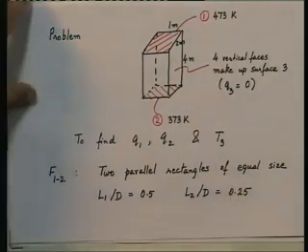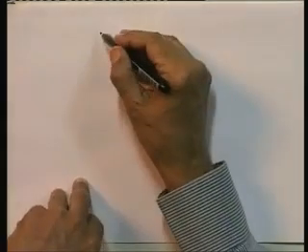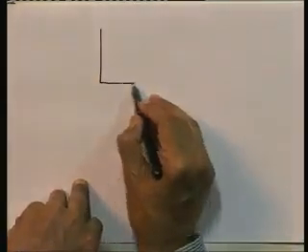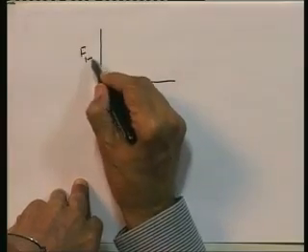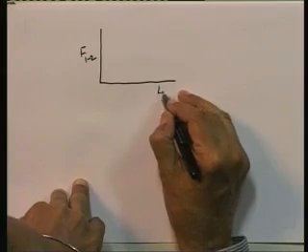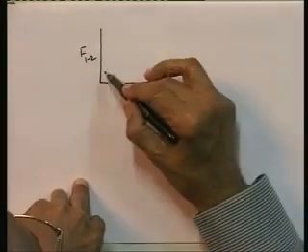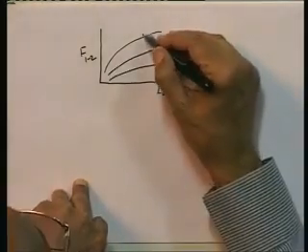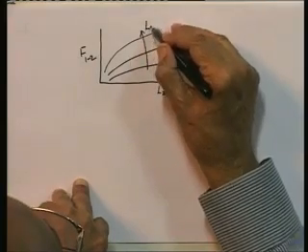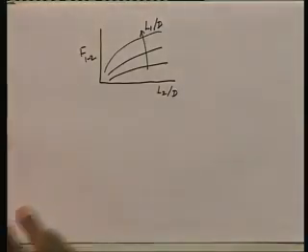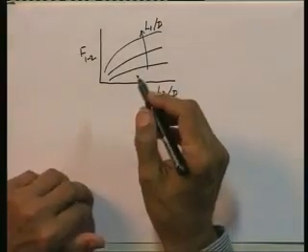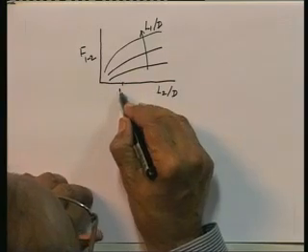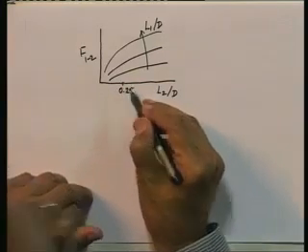Okay. So, now go to the graphs. The graphs give the value of f 1 to 2 plotted. All we have is a plot like this, f 1 to 2 is plotted against L 2 by d, and there are different graphs like this for different values of L 1 by d. So, in this particular case, go to the value of 0.25 here for L 2 by d. Okay.